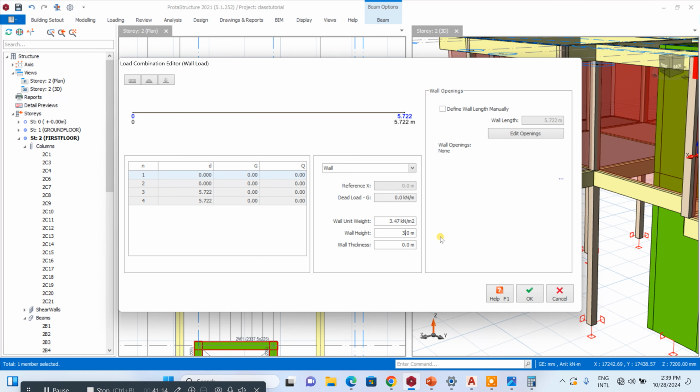So we don't have issue with the columns. So I'll just go to my beam. So your roof beam is actually supposed to be 300, but it all depends on the span you are using and the load which the roof beam is going to carry. So in this case, I'll be using 450 because of so many of the parapet walls at this level.